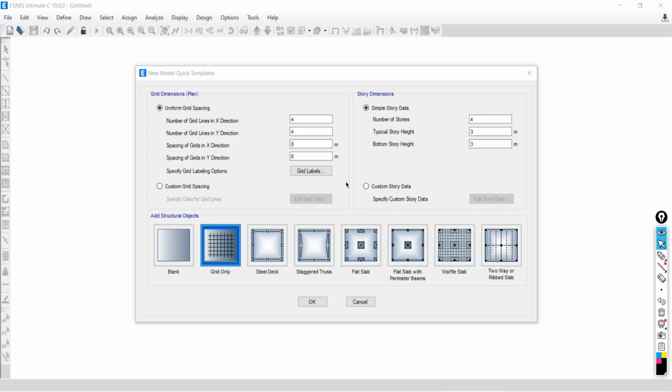Plus, you don't need to prepare everything manually, point by point, in the software. Both of the other methods are a little different and require more steps to prepare the grids, but ETABS will automatically give you default templates. Using these templates you can prepare the grid lines in the software. This is the second option.